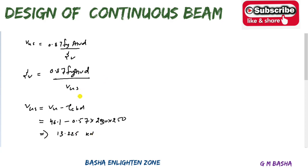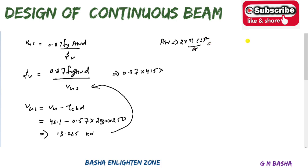Then here, please substitute this value, that is 0.87, fy will be 415, and again for Asv, here I am choosing 6 mm diabars, 2-legged. Two-legged 6 mm bars means 2 into pi by 4 into 6 squared. So if you simplify, you will get 56.55. So here I will get 56.55 in the place of Asv.